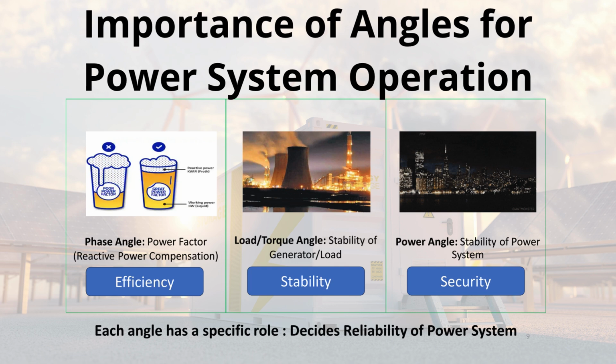And the phase angle, you link that to power factor. Exactly. Phase angle is key for managing power factor locally, which in turn is all about managing reactive power compensation efficiently. If your power factor is poor, you're pushing too much total current, MVA, for the useful MW you're delivering. That means higher losses. Managing phase angle helps optimize that. Makes sense. And the load torque angle?